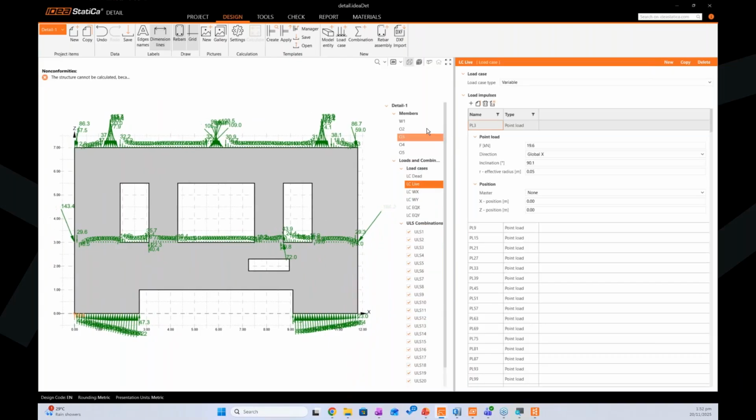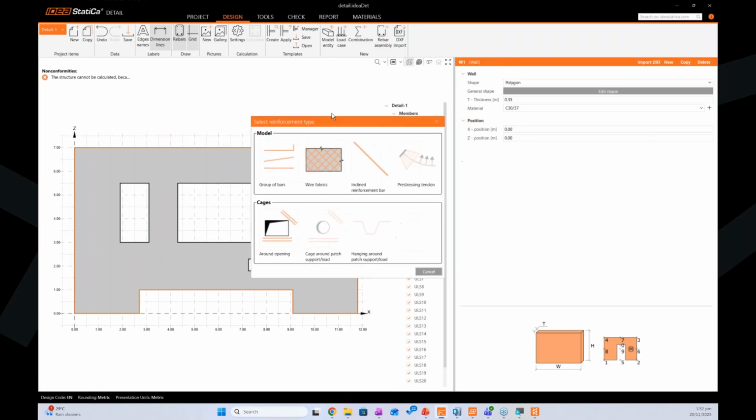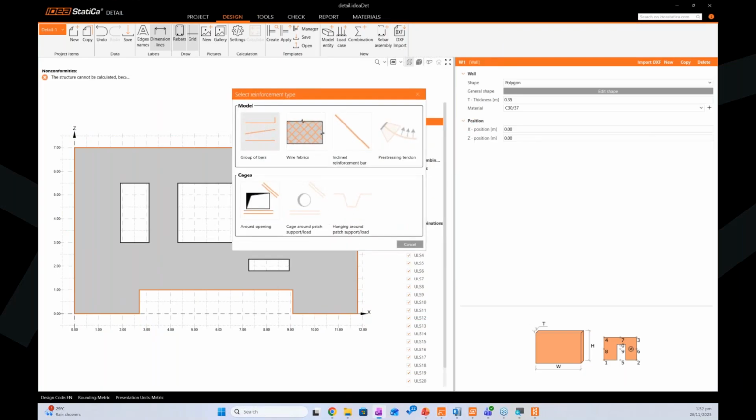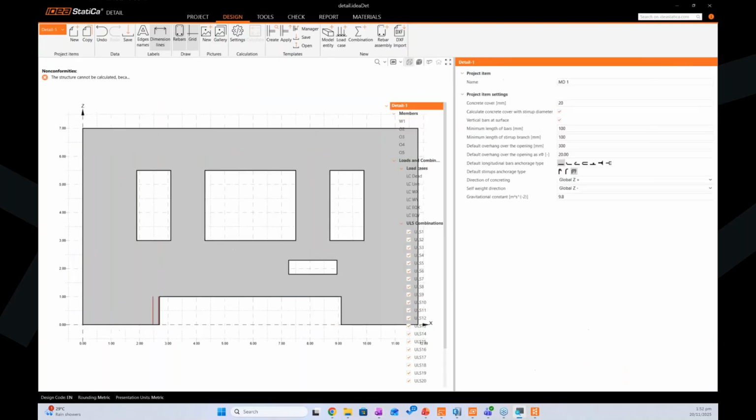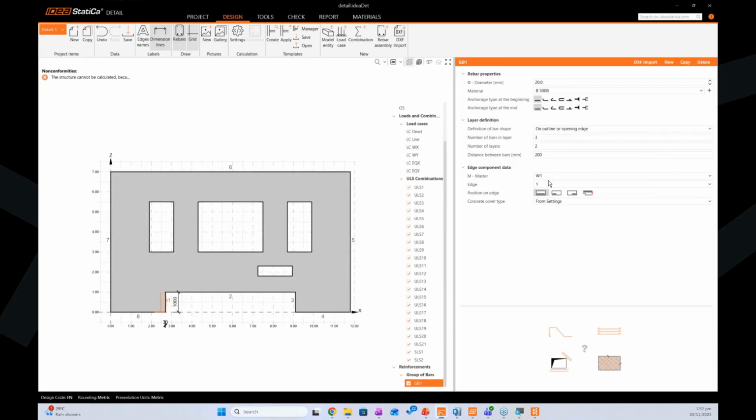And yeah, so then we can start the analysis by putting in some rebar. So you just click this one, rebar assembly. I want to put a group of rebars. Then you can just start putting in where you want it to be. Using the edge one, I want to put a vertical rebar from the bottom wall first. So I just do this. Then I put some anchorage length of 1 meter extension.